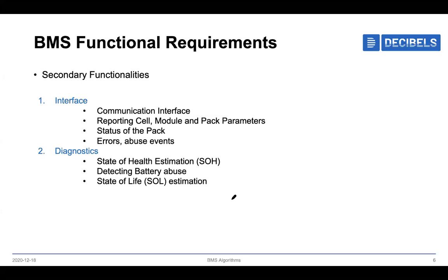So some research work is still going on on how we can implement SOH into the BMS. Finally, it also has to show errors, abuse events, and all those things. Coming to the diagnostics, one is state of health and the other is state of life. These are the two important parameters. Finally, both terms refer to the same thing, which is the health of the battery pack.